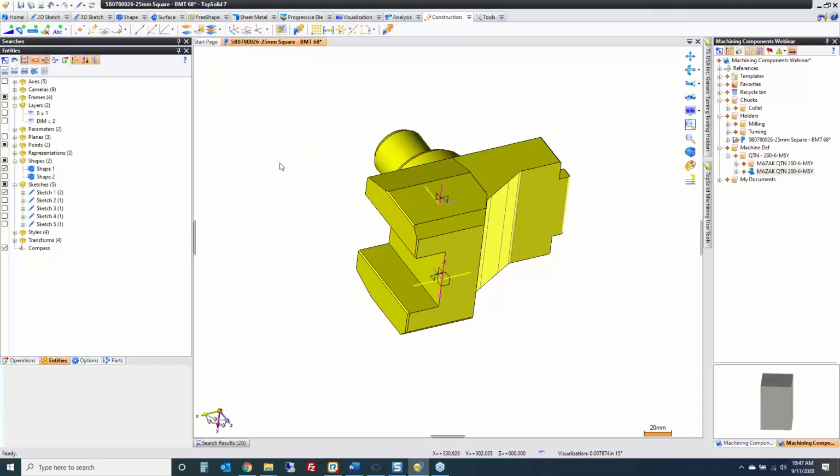Last step I'm going to do is publish these frames, and I'm going to publish them with specific names so that I know what they are. If you want to, before you publish them, you can come here and name them. So I can rename this one to be mounting frame, this one to be left or neutral tooling frame, and then this one to be right tooling frame. I'm a big fan of naming important elements that you create in the software, because when you come back to them later, you can know what they are just by reading.